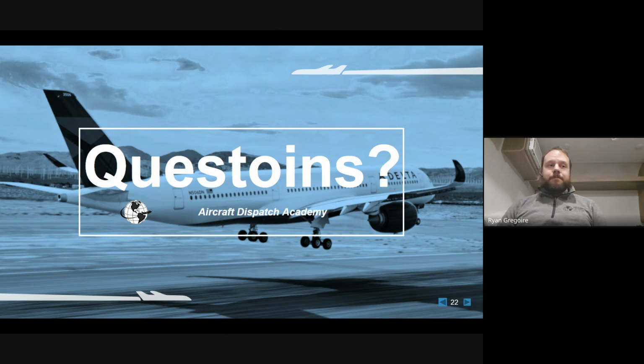something's not going to flow from one piece of software to the other, no matter how integrated they make all of these systems. There's going to be a discontinuity at some point when you are dispatching, where something's not going to match up between what's shown on the aircraft and what's shown on the dispatch release. Being aware of when that happens matters, because if you dispatch that flight, now you've dispatched an illegal flight. You don't know which one is accurate. So making sure those pieces all line up is a big one that you will experience in the real world.